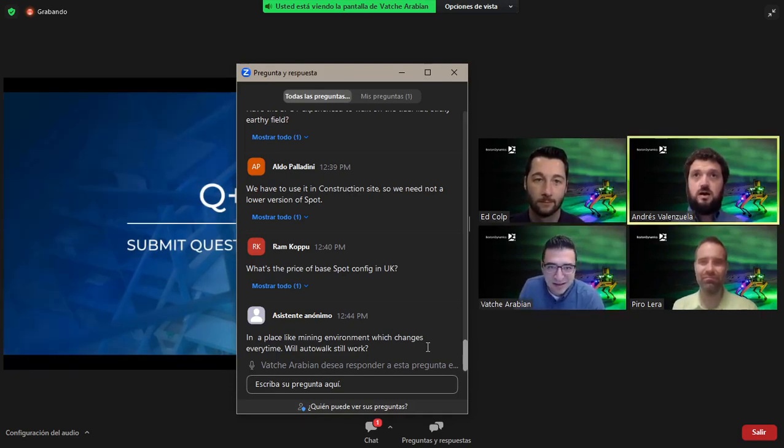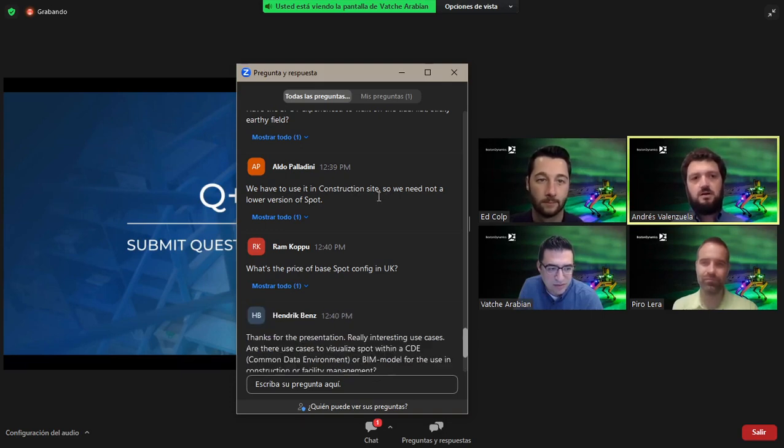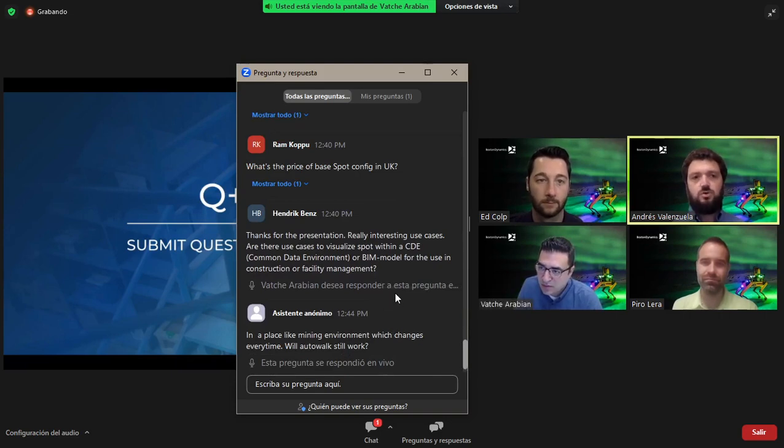Sure, yeah. So the particulars of how the dynamic balancing works are all kind of hidden under the hood and abstracted away. The arm is a 6 degree of freedom manipulator, and you'll have full control of that, both in Cartesian control of the end effector, as well as joint level control. And we also have an impedance control mode for the end effector, which lets you do actions like when we were pushing the tool into the breaker, where you need to be compliant in some axes and stiff in others.